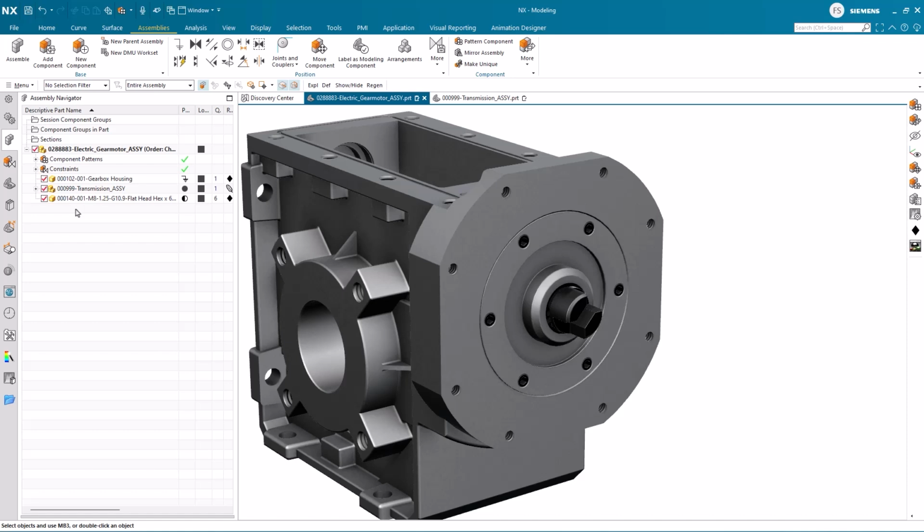As components need to be properly constrained in the way they behave in the assembly, we noted that we are able to check if and how they can move by using the Show Degrees of Freedom tool. To create multiple copies of components in the assembly, we used both the Move Component as well as the Copy and Paste option, where the latter allows us to reuse already defined constraints.